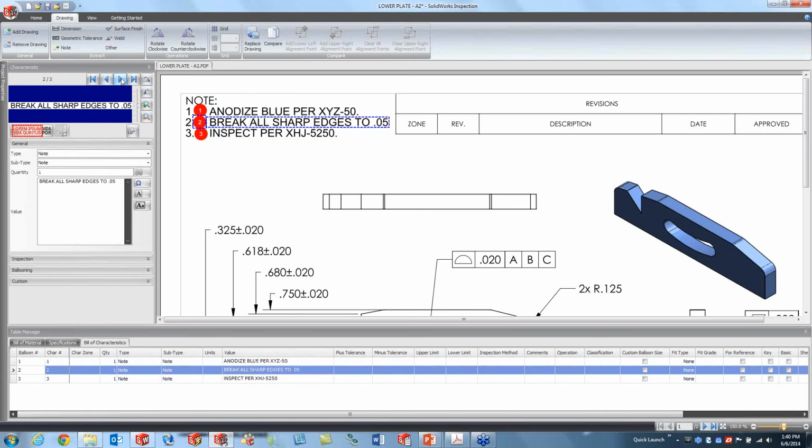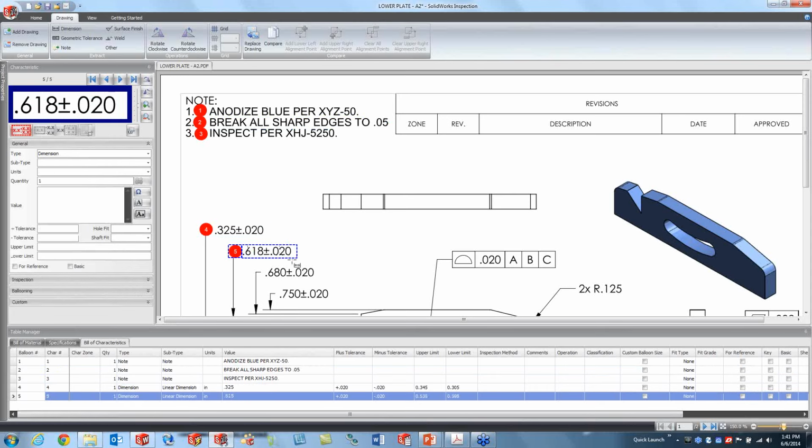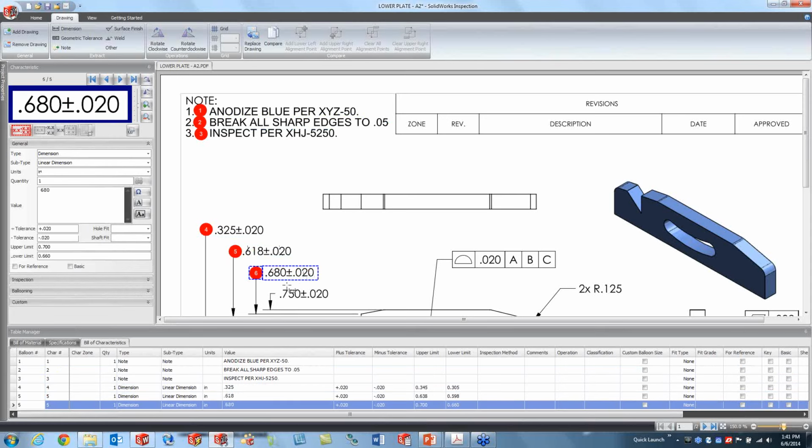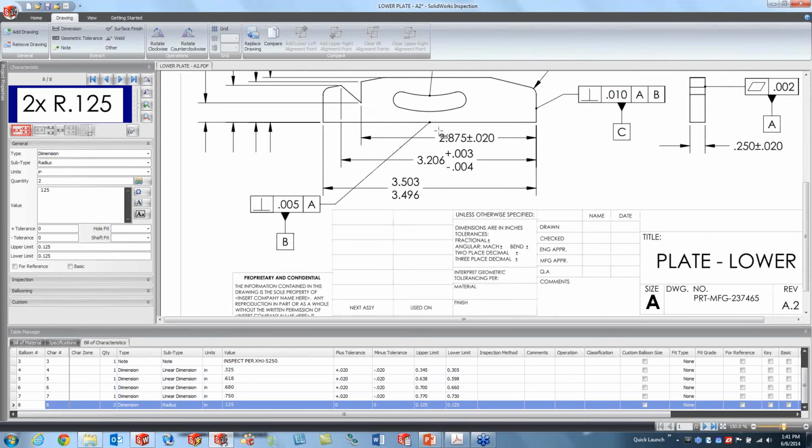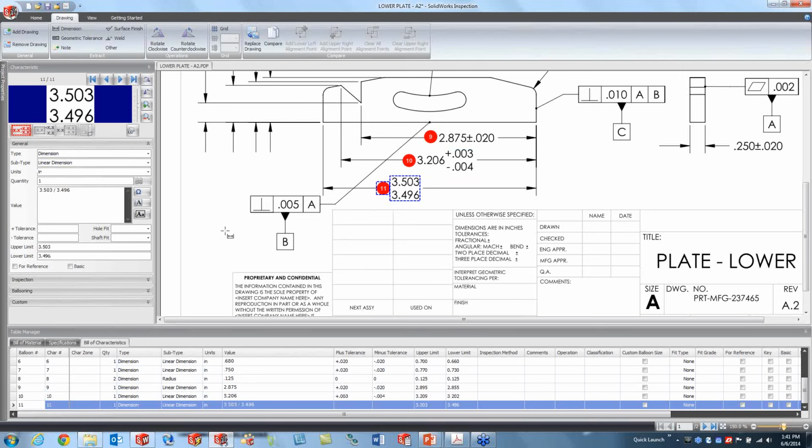Then what we want to do is get into the dimensions themselves. So again, using another tool or using our hotkeys, as you can see from the tooltip here, Control-D, Control-G, Control-N, very predictable. We're going to grab our dimensions. Same thing here: we just want a window as close as possible around those, and as it does, it will do a screen grab and optical character recognize that screen grab, so we want to be sure the capture grabs only what we need. It's even filling out the other properties based on what it sees on the screen. Now left to right, right to left doesn't matter. It's whatever makes it easiest to grab the data accurately.